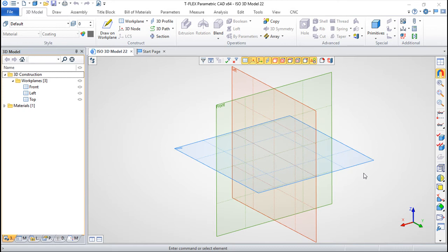The model inserted in this way becomes a normal operation of CAD. Remember, however, that an external model that represents an assembly or is made of several operations becomes a single object upon the insertion inside CAD. We need to do further manipulations over this model to separate it into several operations.